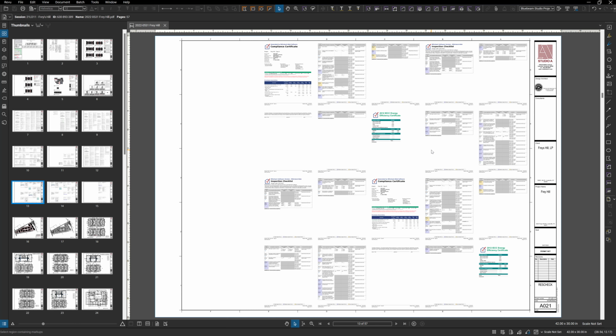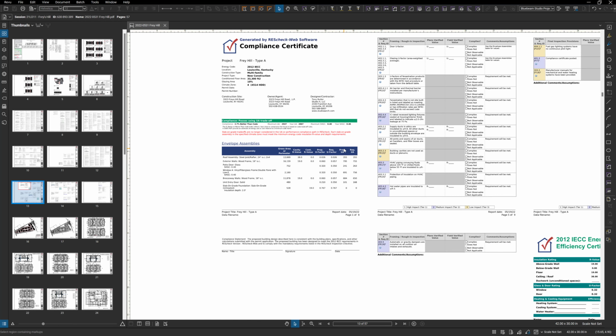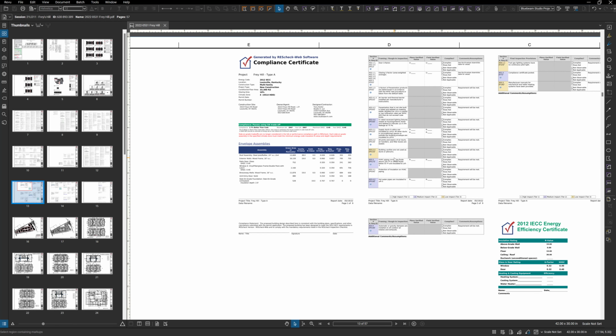But again, when it comes to the energy code, the IECC, they allow you to do 3 stories or less, residential is allowed to have a Rescheck. When you do a Rescheck, things that I see missed a lot are either not really understanding the assemblies that you are using, and people not going through and doing the mechanical and envelope checklist that are a part of those Reschecks. Again, I've done a deep dive on how you do a Rescheck and how you do a Comcheck, so you can watch those videos separately.